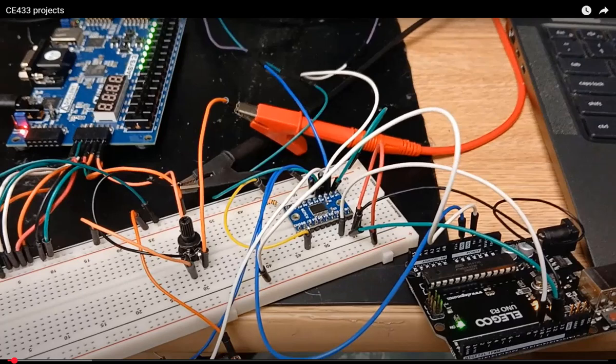So here are the B pins. Here's the VB, short to 5 volts of the Arduino. And then it's B1 to B8. And the last one is ground. So this ground is universal ground. You don't need another ground on the other side. So just ground this one to the universal ground of the entire system, and it should work.